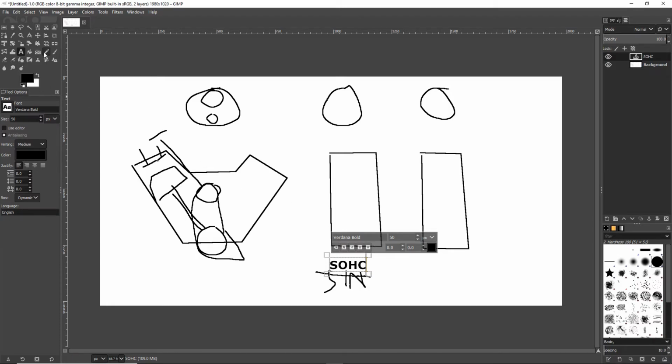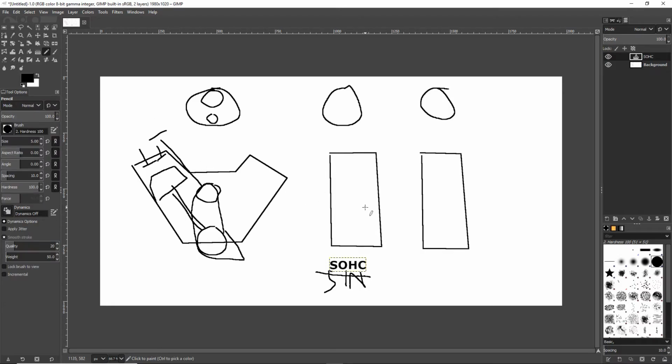So what we did is we got clever. We'll just use the inline 4-cylinder because this is when you saw this and it's the easiest way to do it. So crankshaft bolted to the bottom of the cylinder block, just like over here. Nothing different. Connecting rod, piston. All right, so how do we get these valves to open and close? Well, instead of the camshaft being here in the block, we'll put a camshaft here so that it is directly touching these valves. We'll put a chain or a belt around it like this.